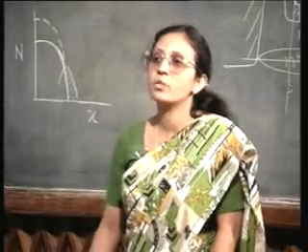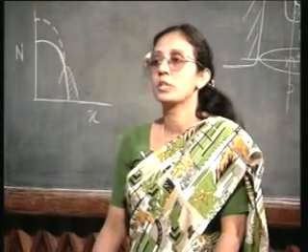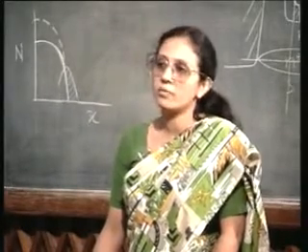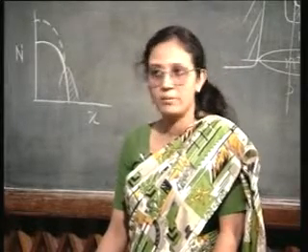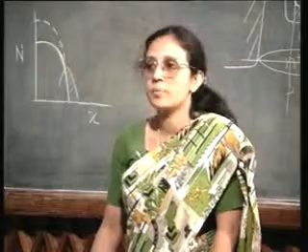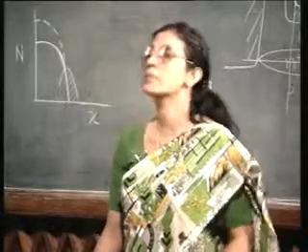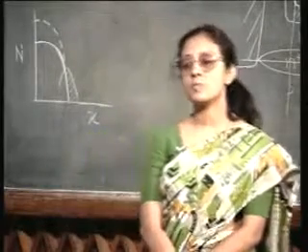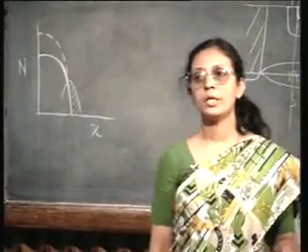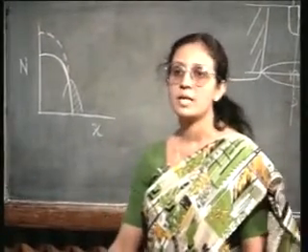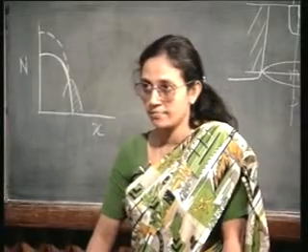It is more difficult to make ohmic contact to a moderately doped N region. So, if you have a PNP transistor where your base is moderately doped, you will have difficulty in forming an ohmic contact. In NPN transistor, there are no such problems, but still for some specific applications, particularly in the case of analog devices, we use PNP transistors as well as NPN transistors.